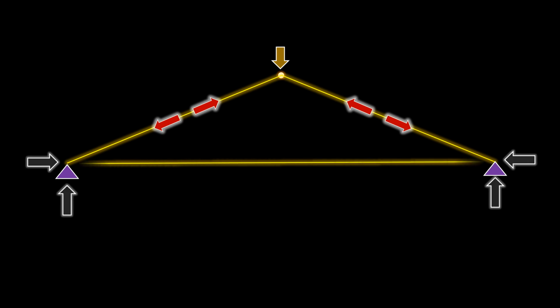What if we bring back the bottom chord? Assuming that the top chord is adequately connected to the bottom chord, we can see that now we have the option to transfer all the outward thrust force at the base of the top chord into the bottom chord so that the bottom chord is in tension. To ensure that this happens, we need to release at least one of the pinned connections laterally so that no reactions will develop. In structural analysis, this is done by using a roller support.